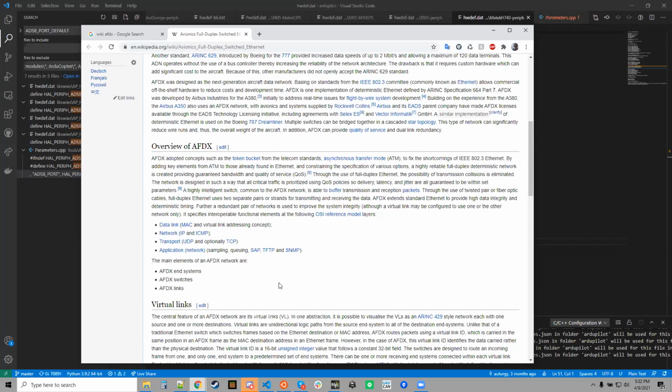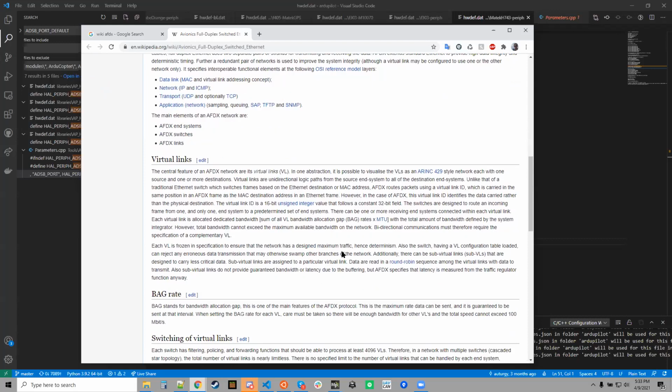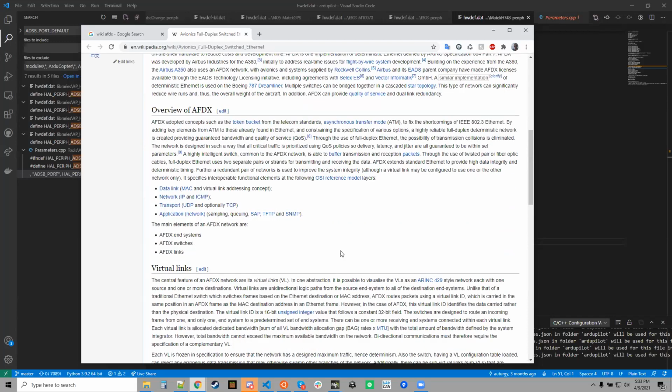And there are cameras and sensors and stuff that are Ethernet only, because of the sheer massive amount of data that they generate. It'd be really great as a protocol for companion computers, that sort of thing. That's been the argument too, is the right tool for the job. Is the autopilot itself the one you want to be feeding hundreds of megabits of LiDAR data to, or is that some sort of Linux computer that's got gigs of RAM that can handle all that?